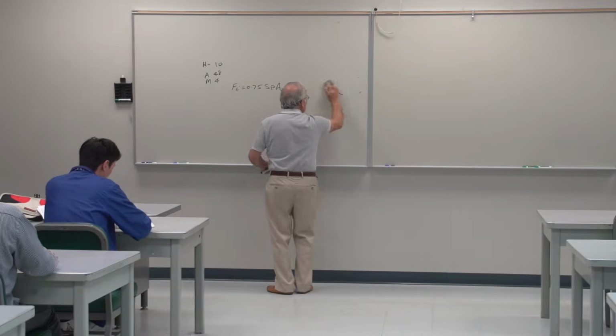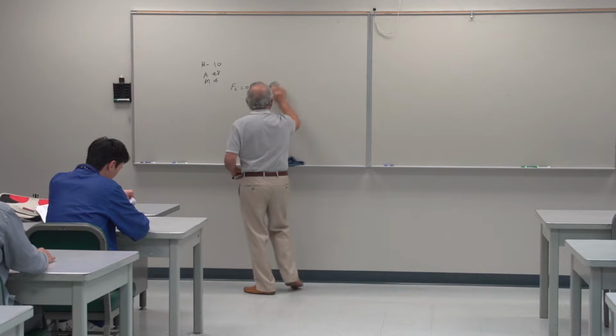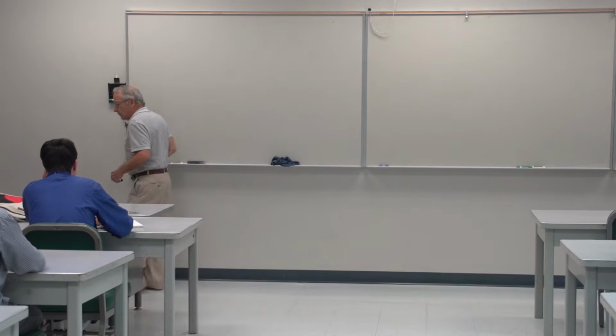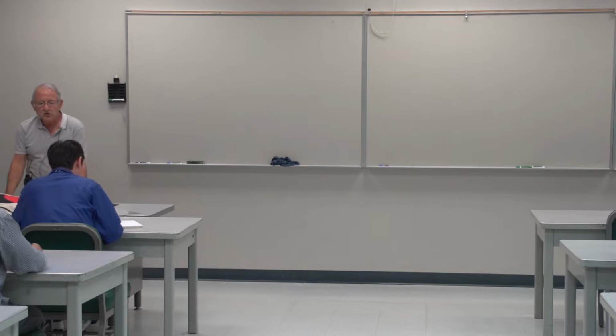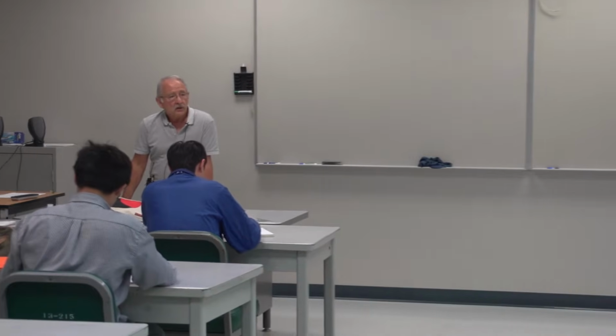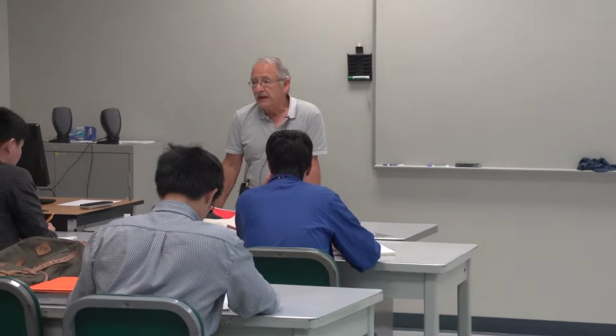One is the direct application of the load itself, which is divided amongst the rivets equally, and the other comes from any moment that that force may create.